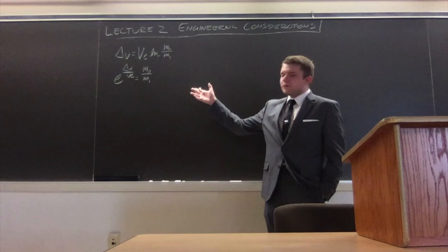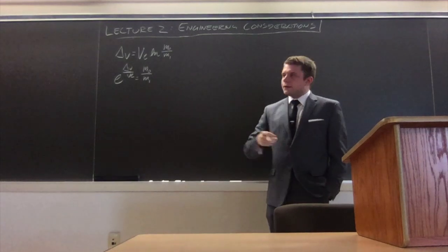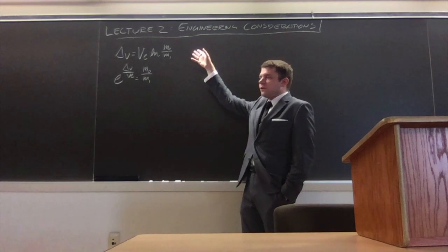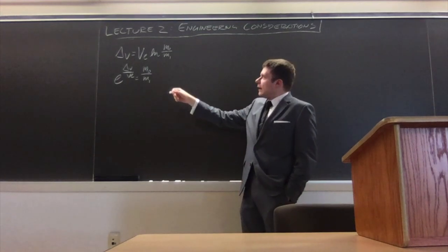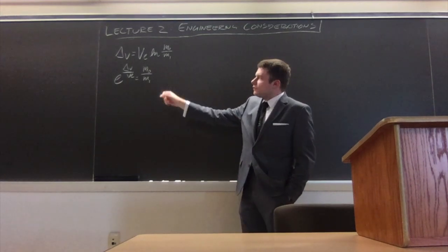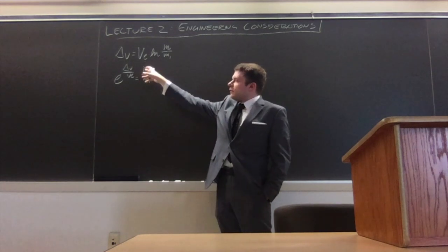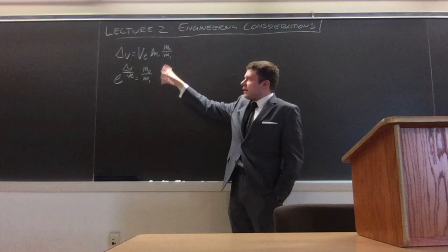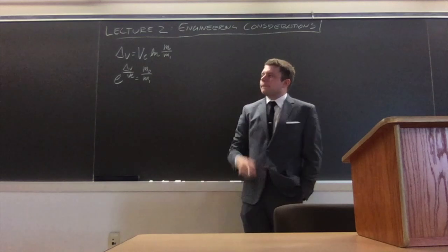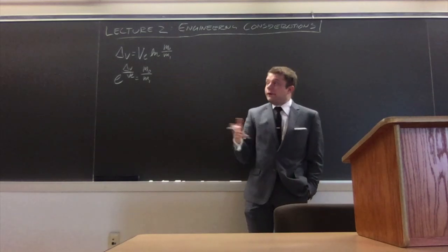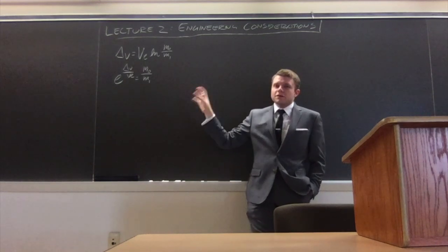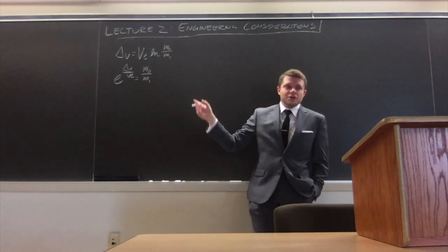So these are two different ways to look at the ideal rocket equation. You have the more traditional format, which takes the effective exhaust velocity and relates it to the starting total mass and the final total mass. And you have the somewhat untraditional version that relates the ratio of the delta V and the effective exhaust velocity, raised to the power of e, to the overall mass ratio of the rocket. And as I said, this really does work. This is really how rockets function. You can define how their velocity changes based off these two equations in some way, shape, or form.